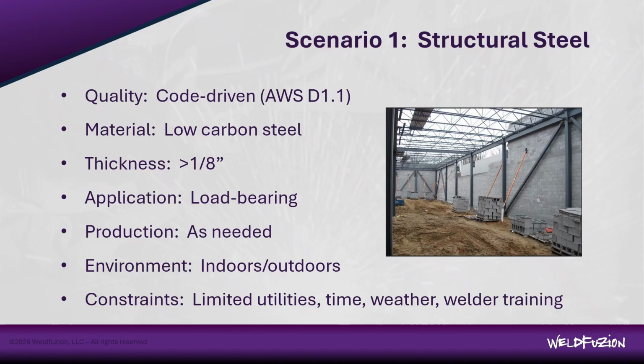If we look at quality and inspection criteria for this industry, it follows the AWS D1.1 structural welding code for steel, which defines the pre-qualified welding processes and procedures that are acceptable to use without any testing, and it specifies base and filler metal combinations, so it really gives you a head start. It also provides provisions for qualifying other processes like TIG in case you need to use it, and procedures for welding, and it also provides provisions for qualifying personnel, right?